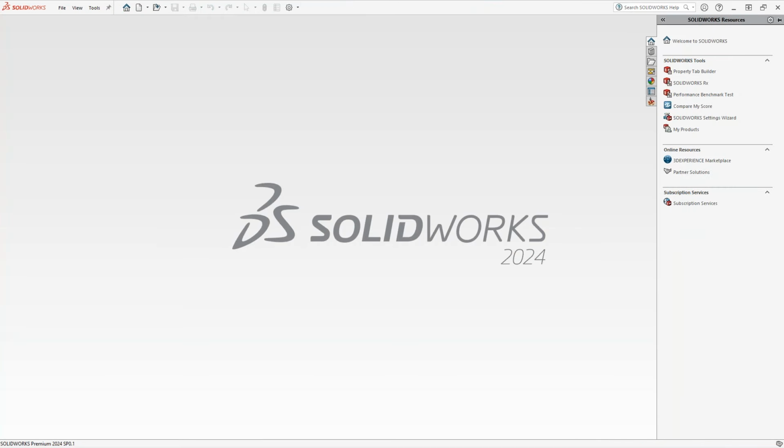Now, before opening a Mill-Turn project, I want to show you another feature inside the toolkit. I couldn't show it till this moment, and you probably remember that I have worked on two components in this part, right? So we defined one holder in station 21, and also we added one extension collet to it, right? But this definition was executed on the level of the part toolkit, everything related to a part. It is not in my vault. It is not in my database that is on the lower level.